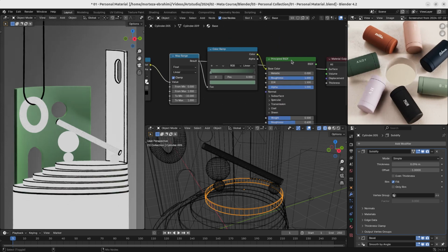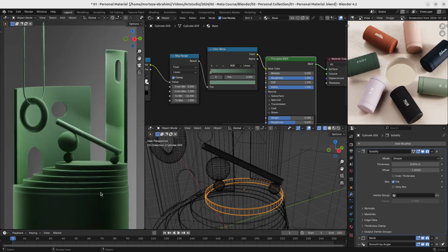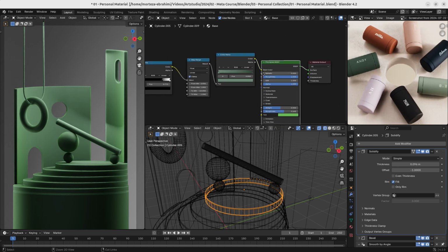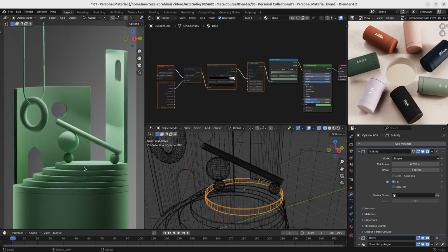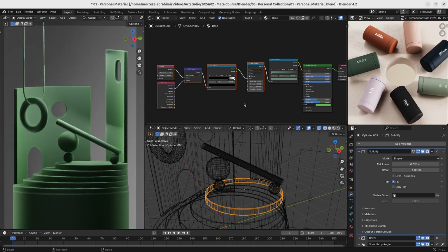Now let's Ctrl Shift and left click on Principled BSDF and you will see it, and it actually is really interesting. So we can just select everything, press M to mute those. It is before and after. Wow, it's a lot different. So that's great. We can press Ctrl S to save this. So this is a really important tip.